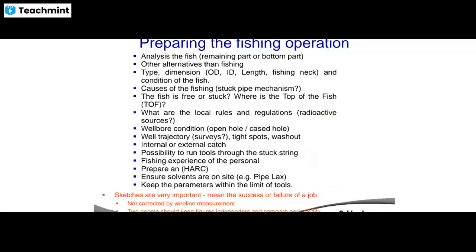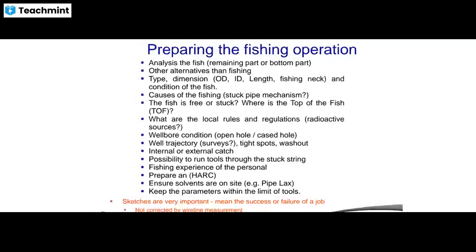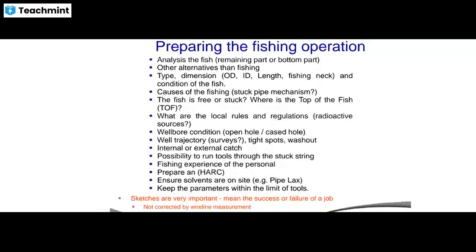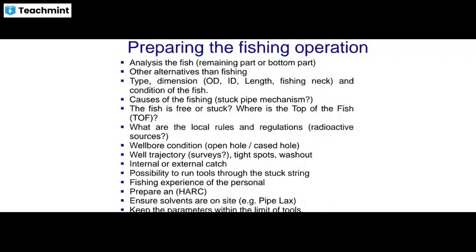Then preparing the fishing operation. So what is the preparation for the fish? Analyzing the fish, that is the remaining or bottom part. Then other alternatives than fishing, then type, dimension, outer diameter, inner diameter, length, fishing neck and condition of the fish and causes of the fishing. Stuck pipe mechanism, is the fish free or stuck, where is the top of the fish, TOF, what are the local rules and regulations, wellbore condition, open or cased hole, then well trajectory, tight spots, washouts,